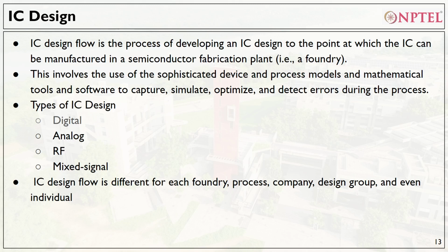What I want to discuss in greater detail, not in much detail, right, is the IC design flow. The IC design flow is the process of developing an IC to the point at which the IC can be manufactured in a semiconductor fabrication plant, right? And this involves the use of sophisticated devices and process models and mathematical tools and software to capture, simulate, optimize and detect errors during the process.